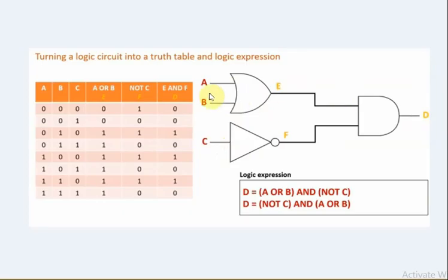While this is on, the firefighter should be able to turn it off. So now only the firefighter is activating the signal. That means if the firefighter inputs a signal, activating means 1, no? Then it should go through the NOT gate, then this becomes 0, this is the AND gate. So even though this is 1, if this is 0, the signal is 0, this gets off. Right, now it should be very clear, right?